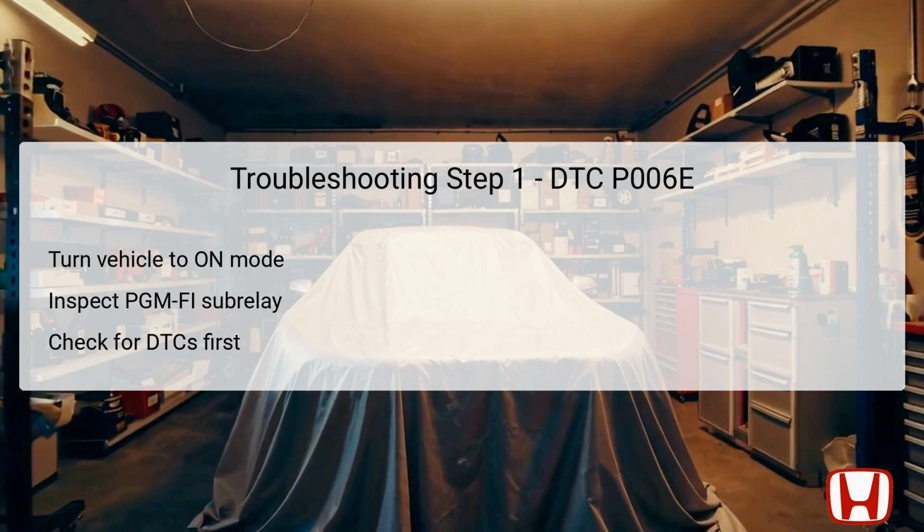Next, confirm whether there are any DTCs related to the PGM-FI subrelay, such as P1658 or P1659, which may indicate underlying issues that need addressing before focusing on the power supply circuit. Performing this initial step sets the foundation for the entire troubleshooting process.